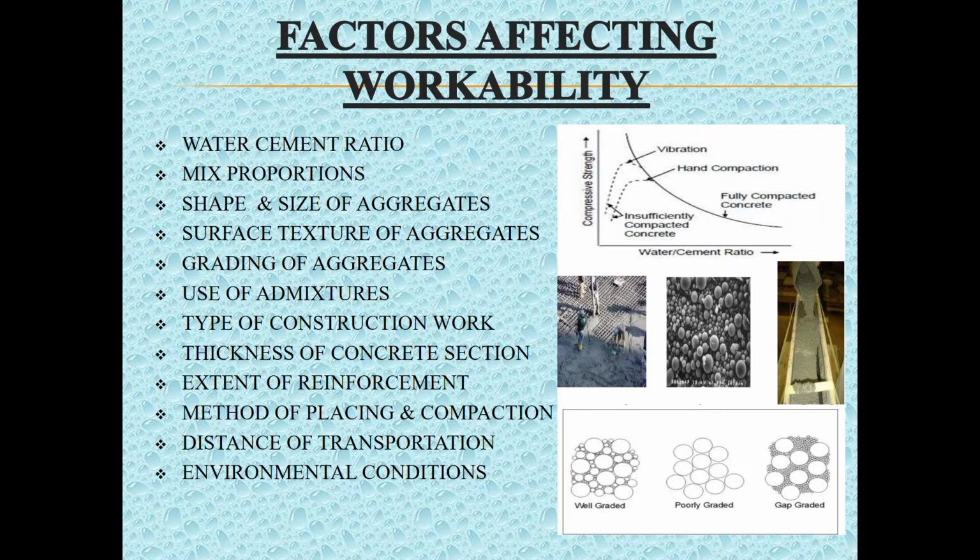Section, size, amount, and spacing of reinforcement have an effect on workability. When a section is narrow, highly workable concrete is desirable to obtain full compaction through a reasonable amount of effort. When the section is crowded with steel reinforcements and spacing of bars is relatively small, compaction can be difficult and hence highly workable concrete is recommended in such cases.